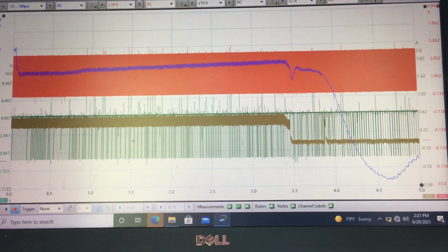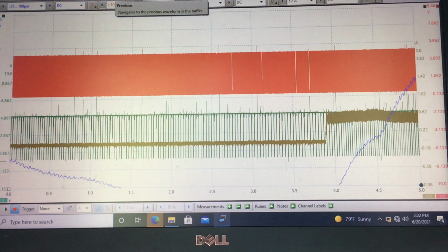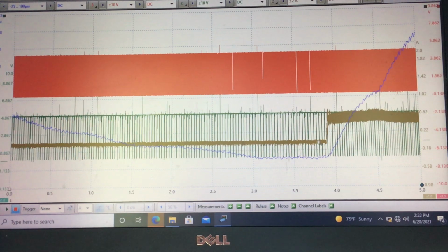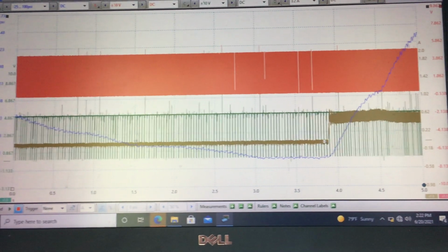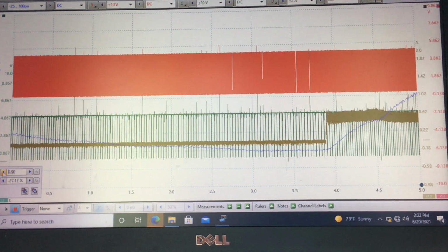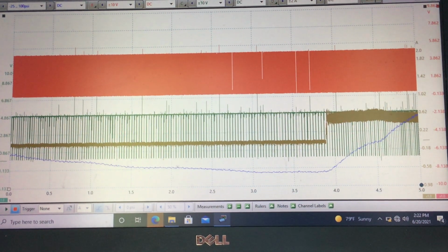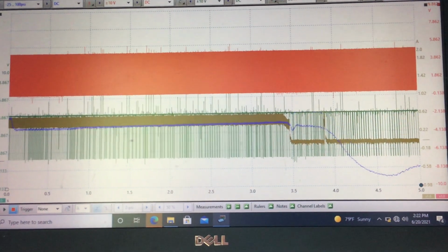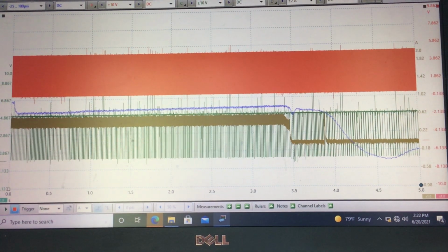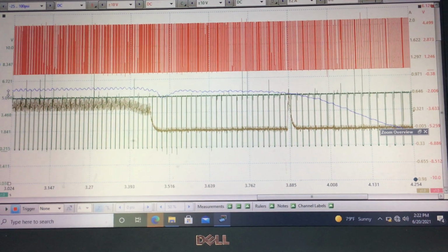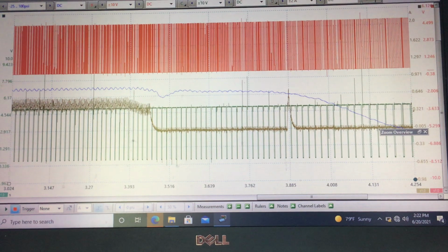And let's take a look at oil pressure at the moment. Okay, well, we see oil pressure going up here. We see the PCM has commanded the spool valve to open more to get more oil up to the actuator, and the oil is starting to flow into the actuator, and we can see it here. There's our oil going up, and the next capture right here, oil pressure going down as the RPM goes down, because variable valve timing is contingent on RPM and load. PCM decides when it wants to phase that cam. It's got control of the solenoid.